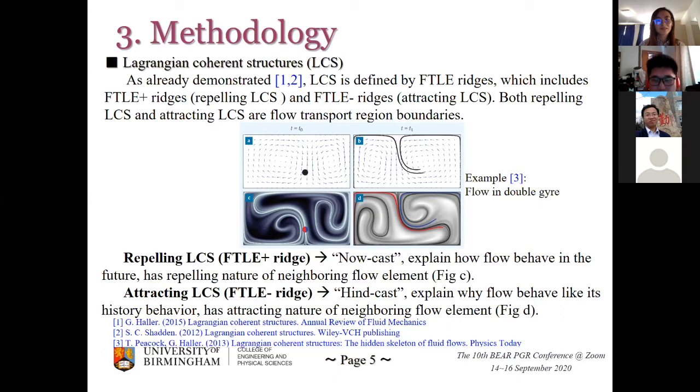And also, I have a second question. Because we know that in turbulent flow, there are different scales. For example, the Reynolds-averaged scale, and if we go deeper, it is LES, large eddy simulation. And now the most cutting edge is DNS, direct numerical simulation. I wonder which scale you are using to simulate the chaos in your flow reactor.